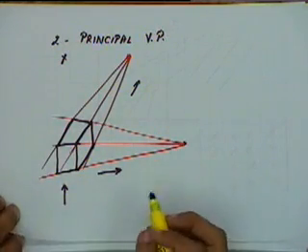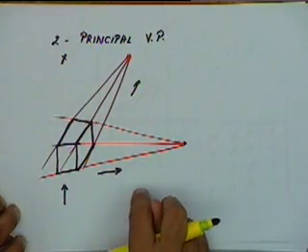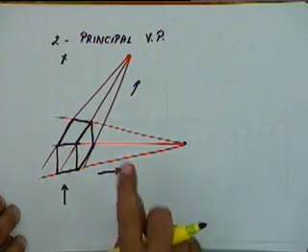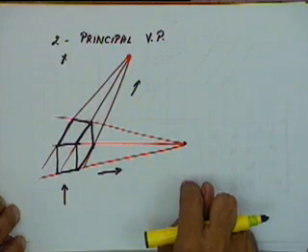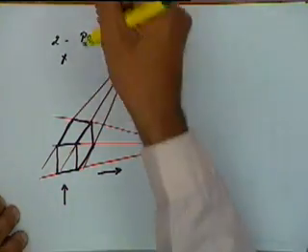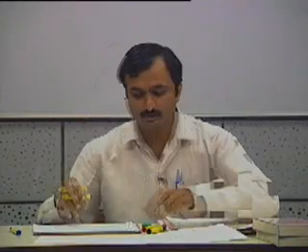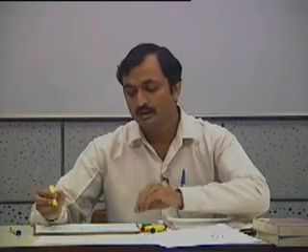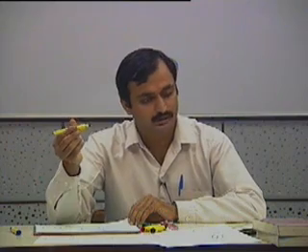Okay, so traditionally whenever a perspective view is drawn, the principal vanishing points are displayed along with it. That gives the designer a good feel of the orientation of the plane and so on. One would always like to show the principal vanishing point, or if in a particular object a face is parallel in a particular direction, then in that direction where the principal vanishing point lies, one would normally like to show it.